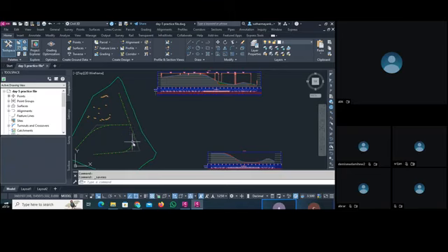When you create the corridor, you can see your road as a working model. Then we check how to assign the sample line, which is the cut section. It is used for the section views, which we call cross sections. Here you can see in a profile and section view, all these things are given: sample line and section views.